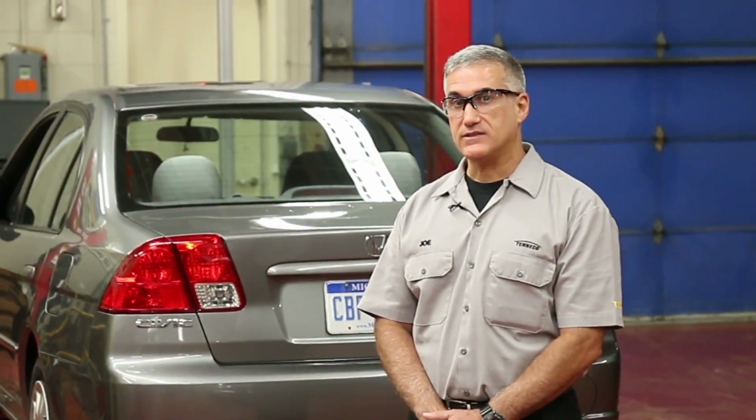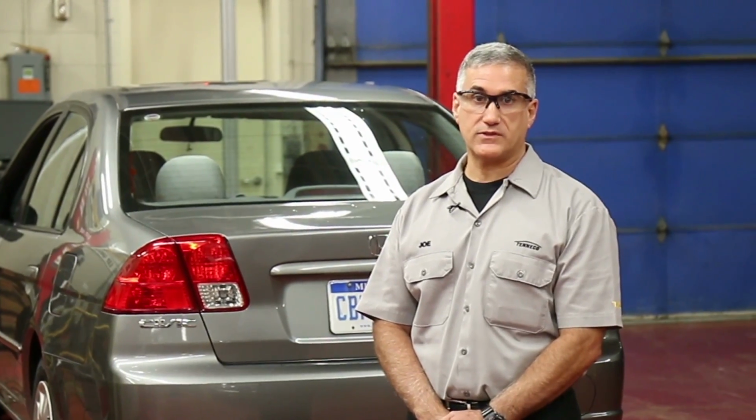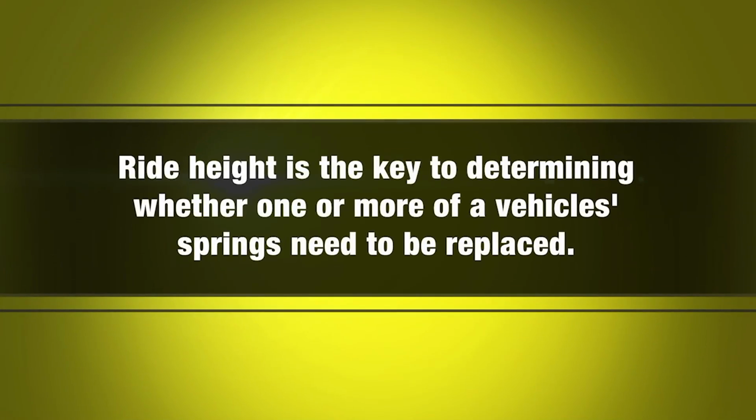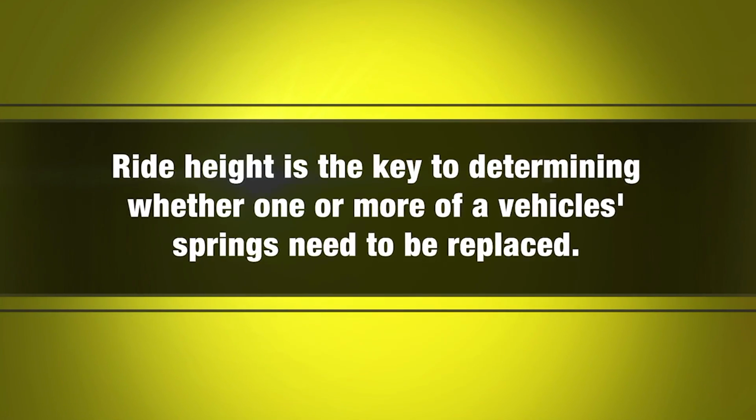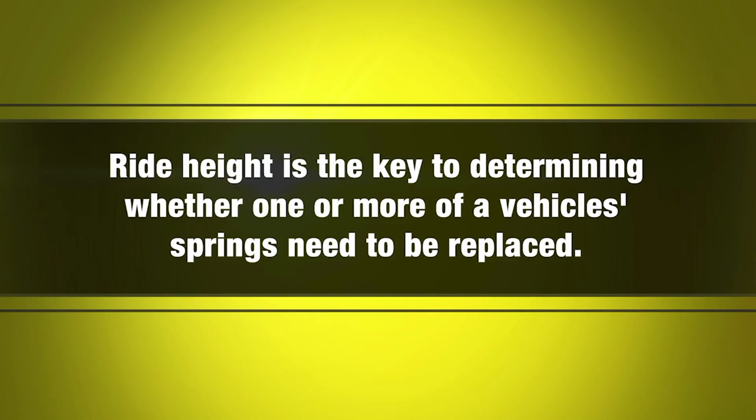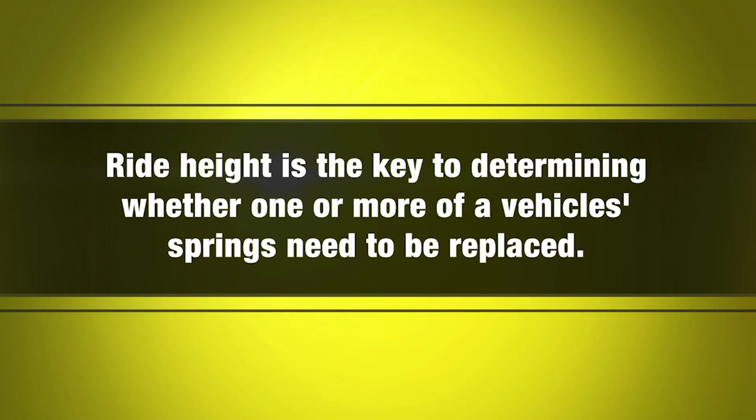Ride height may dramatically impact the alignment, the directional stability, stopping distances, and steering. It's also a key factor in the durability of most suspension components, including shocks, struts, and tires. It's the key to determining whether one or more of a vehicle's springs need to be replaced. However, properly measuring ride height can be tricky.